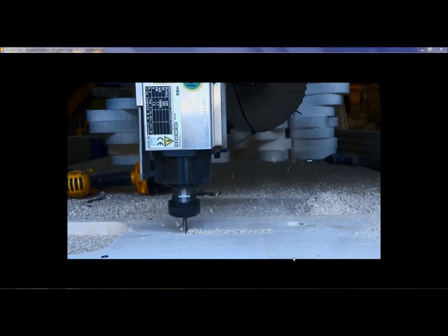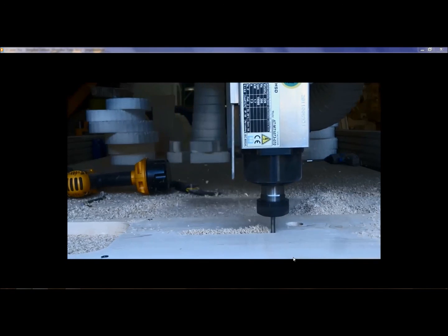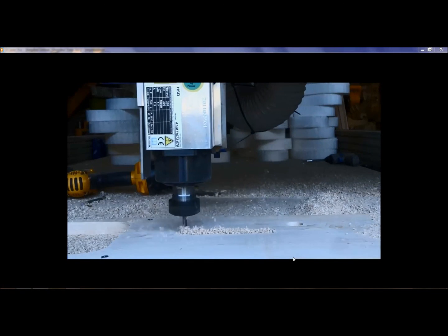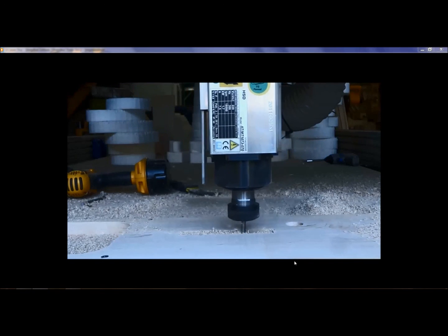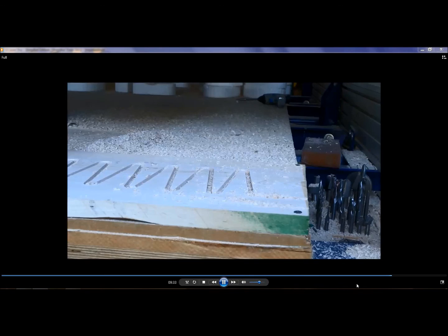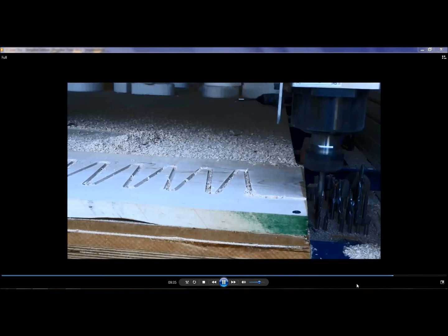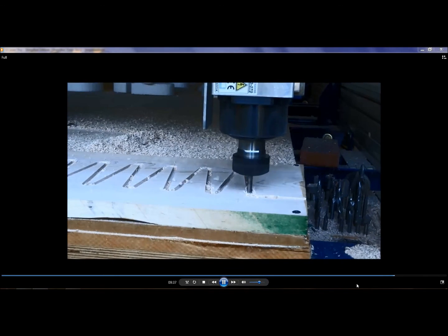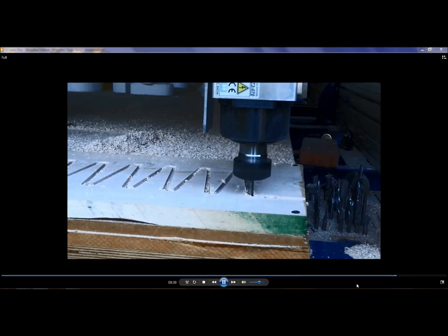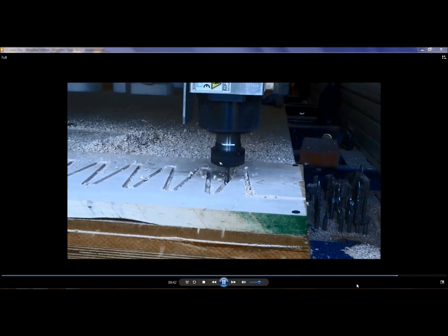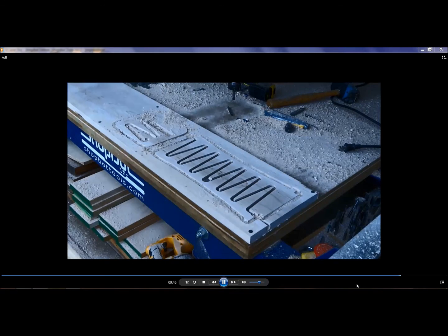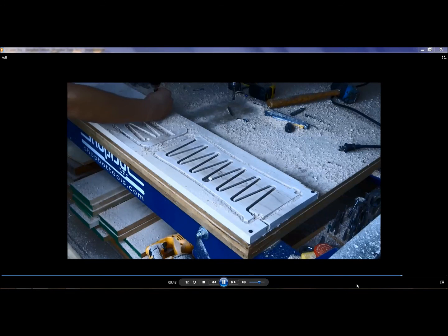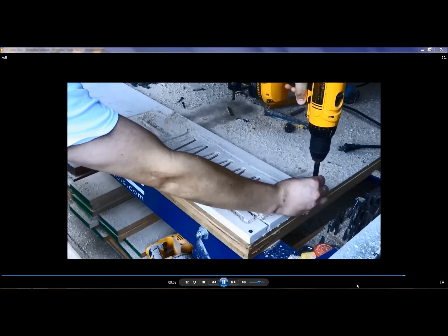Since this is a 1/4 inch bit, I did it in 2 passes. Now it's going to pick back up, ramp again, and then go back down to the next depth. Ramps are real nice as far as wear and tear on the bits. And here again was showing the fluting, with a ramp at the end of the flute. So it went back, ramped back and forth, and then came in with the lead ends.